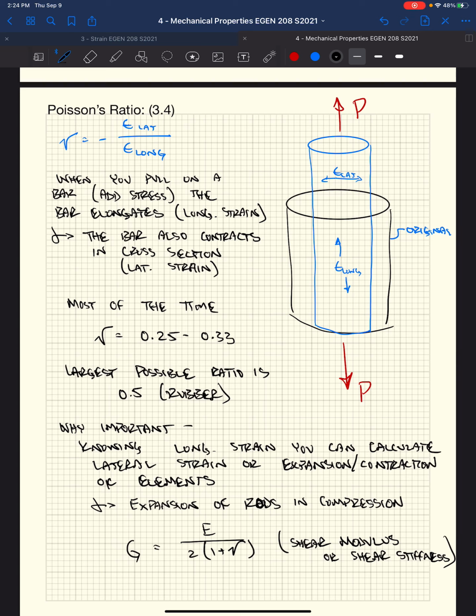And we'll work through some of that here. It's essentially the same thing as modulus of elasticity, but modulus of elasticity is a longitudinal, kind of a normal stress-strain relationship. When we talked about shear stress, we have this idea of shear modulus. Our shear modulus is a function of our Young's modulus, or our modulus of elasticity, and our Poisson's ratio.